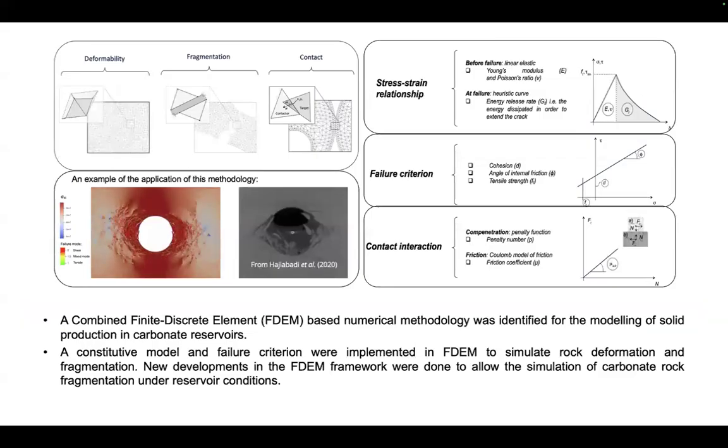The way we tackled this problem was by developing a combined finite-discrete element method that can estimate the breakdown of the solid in the well. So what's the finite-discrete element method? Just a very quick overview. As the name says, it has both finite and discrete element methods. The finite element method deals with the deformability of bodies. Your simulated body is discretized with finite elements, and so you can compute the deformations, stresses, and strains in the body.